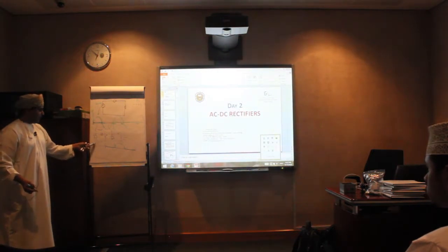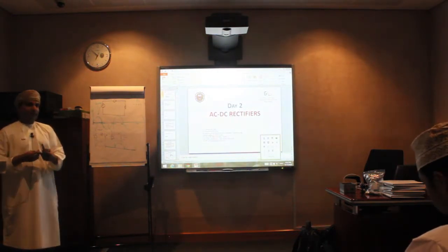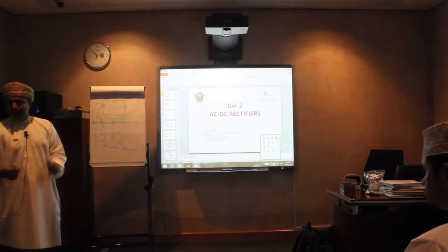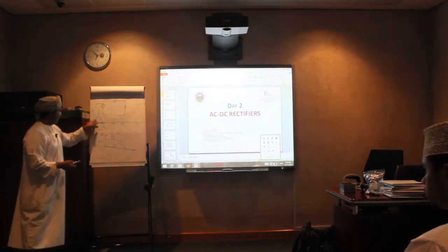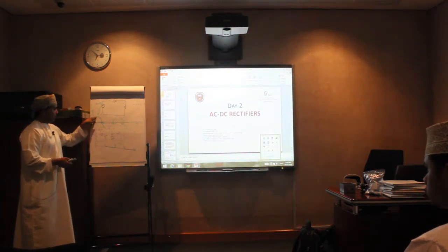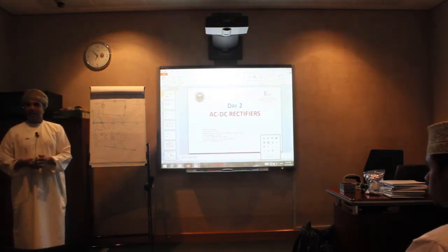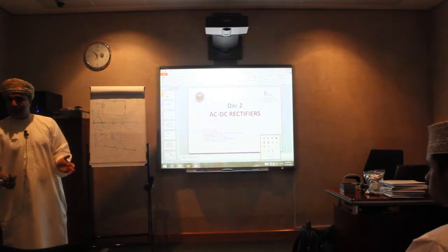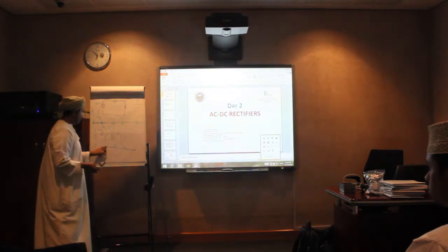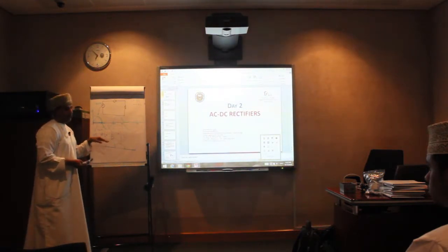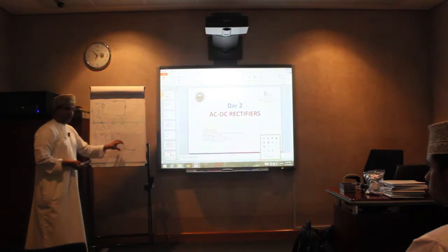That means, in this output voltage here, do we have a negative part? No, right? We don't have a negative part. That means I converted my input from two polarity cycles to one polarity, which is the positive one. Therefore, that means I have a DC output, right? But in this case, the output is not pure DC. It has some harmonic components and later needs a filter to filter those. But now I can get this output as a DC voltage.